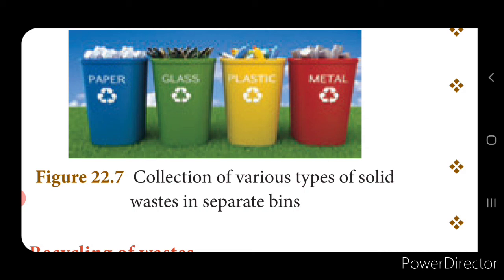If you see the methods of solid waste disposal, the first one is segregation. Even at home we segregate the dustbin into biodegradable and non-biodegradable before we give it to the municipality. So segregation is the separation of different types of solid waste into biodegradable and non-biodegradable. The next one is the sanitary landfill. The biodegradable materials are dumped into low-lying areas and allowed to stabilize for about 2 to 12 months so that the organic matter undergoes complete decomposition.